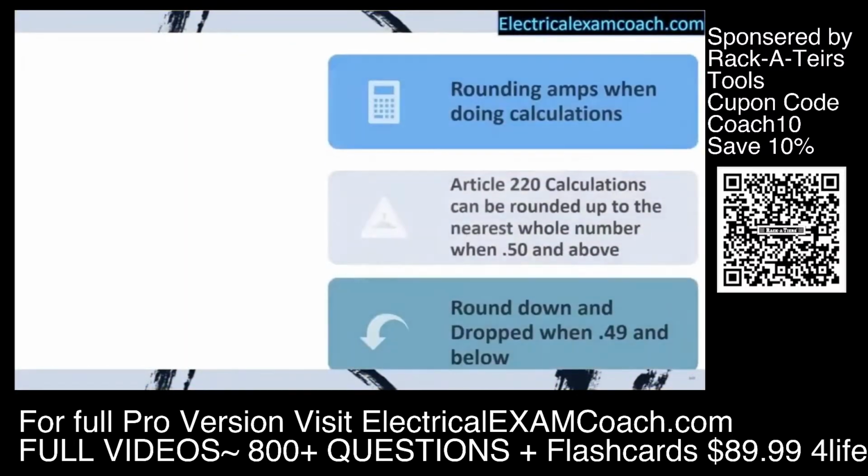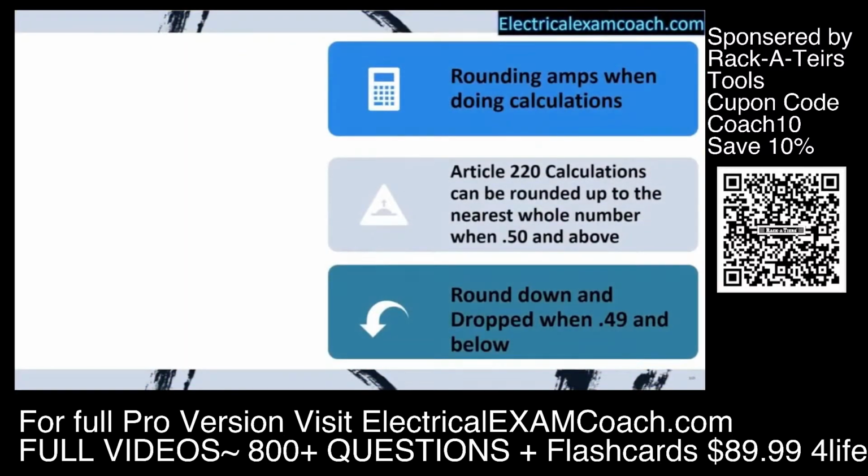In Article 220 calculations, we're going to be able to round up or down. We're going to round up to the nearest whole number when it's 0.50 and above, and we're going to round down and drop it when it's 0.49 or below. I want to let you know, though, that we're only going to do it one time at the end of the calculation. You're not going to be rounding up and down in between each piece, or you'll definitely end up